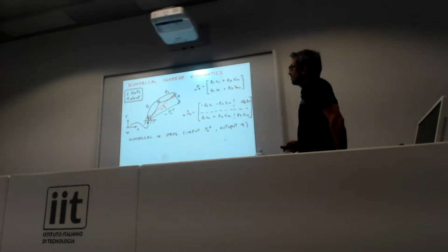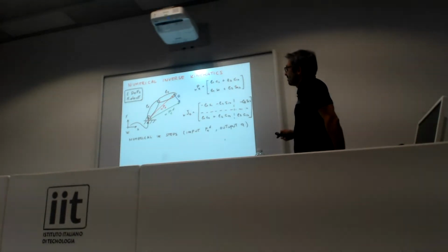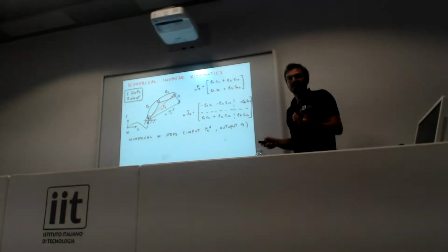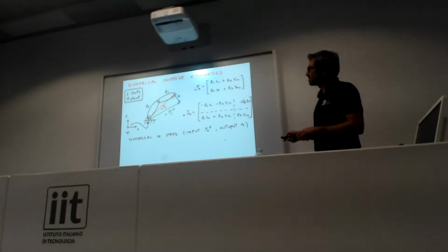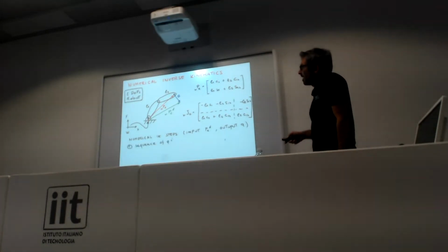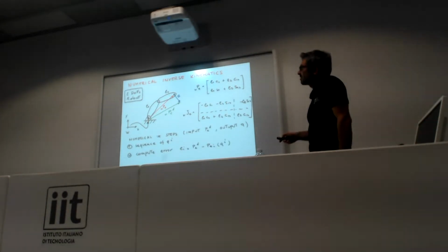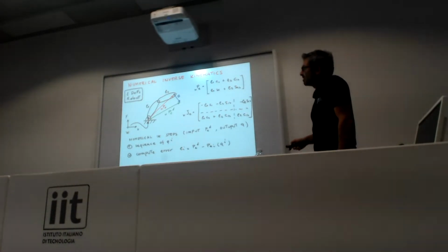The idea of numerical IK is that, having the desired end effector position as input, we want to get the desired joint positions, the set of joints that correspond to it. For this, we consider a sequence of sets of joint positions, and for each one we compute the error.